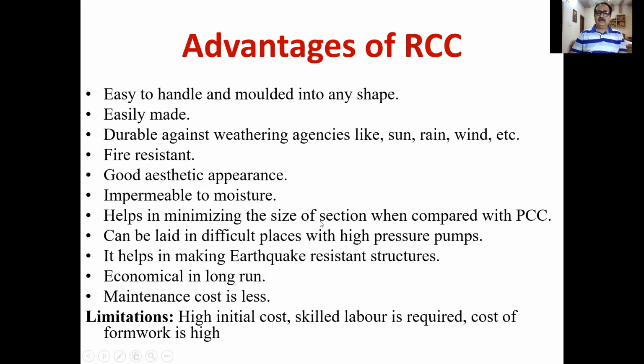It helps in minimizing the size of the section when compared with the PCC. PCC is the plain cement concrete. If we design a section with only plain cement concrete, the size of the section will be high. It will be greater. So to minimize a section, we always use reinforced cement concrete. It can be laid into difficult places with high pressure pumps. As we all know, RMC is now in. So with the ready-mix concrete, we can use these high pressure pumps to place the concrete in difficult positions.